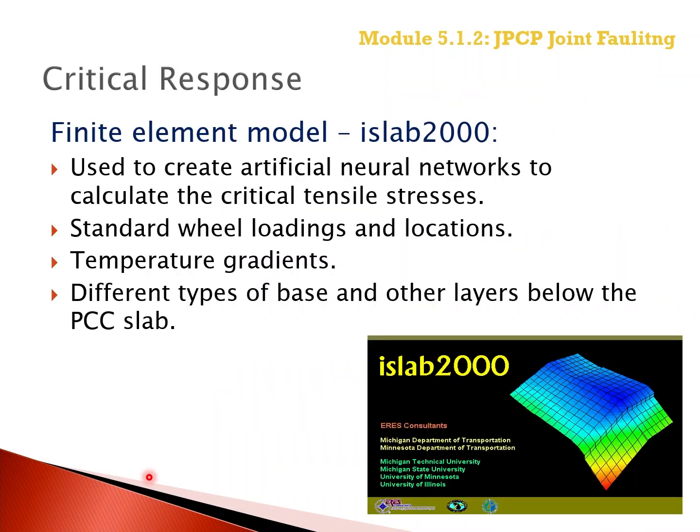Remember from Module 2, ISLAB 2000 is used to calculate the responses of the concrete slabs for designing jointed plane concrete pavements. ISLAB 2000 is a finite element program.